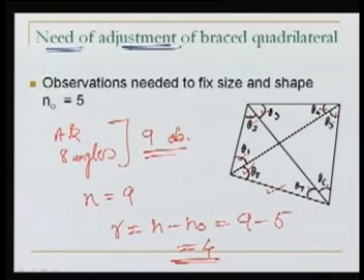Why this redundancy? Because we took extra angles. These are the extra angles. Even if we don't observe these angles, just by knowing the length here and these angles, the problem can be solved. So we have a redundancy of 4 in this particular problem. Because we have the redundancy, we would like to go for the best possible solution. One more thing here.